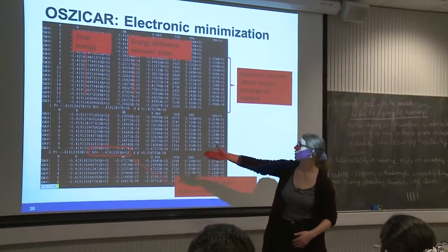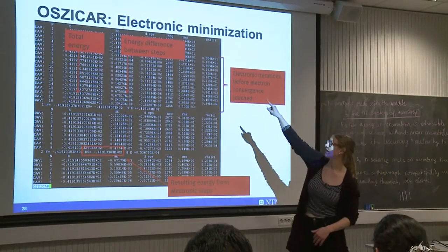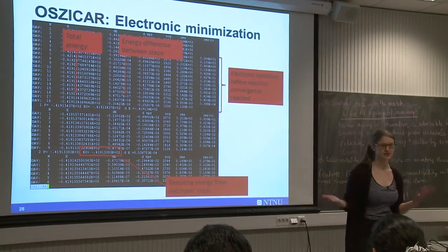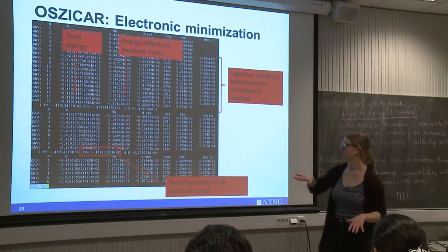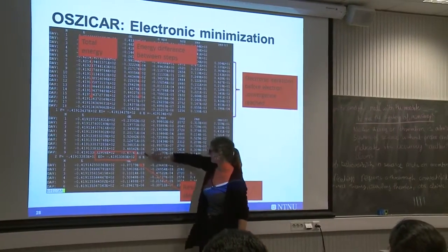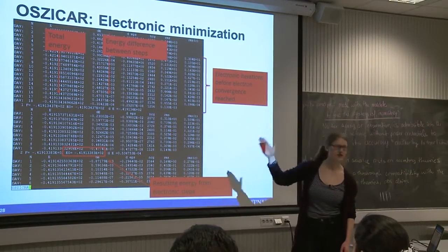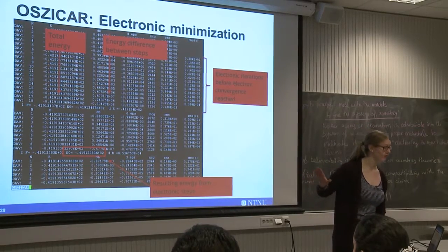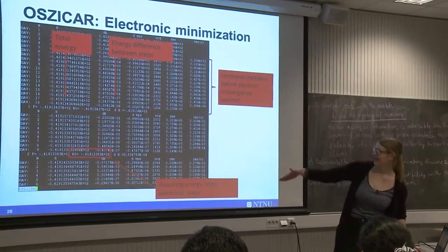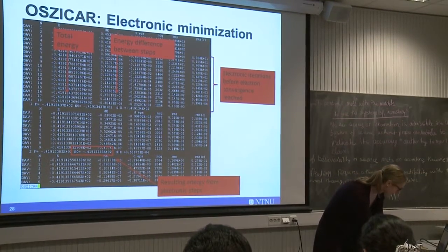So it calculates the total energy, and what you set as a break condition is actually when the energy difference between two calculated total energies becomes smaller than something, then it just breaks out of the loop. So here it's something like 10 to the minus 8, or it might be 7, since it's there. And then you get out a total energy. And so it will continue to do this until it reaches your criterion for the ionic relaxation, right? And so at the end of this file, you have the total energy of your relaxed ionic steps.